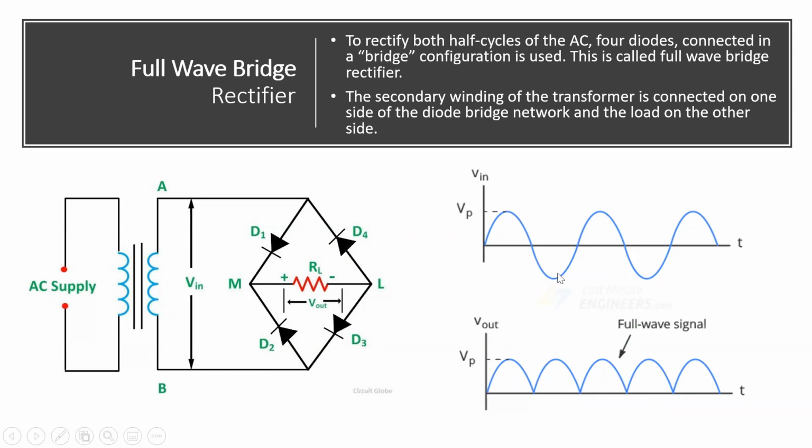Now coming to negative half cycle, the current direction is reverse. So up I have negative, down I have positive. Okay, so now I'm starting from this point B because this is positive now. So I'm coming from here, it reaches here. Through which diode will it go now? D2. So it will go through D2, reached M.